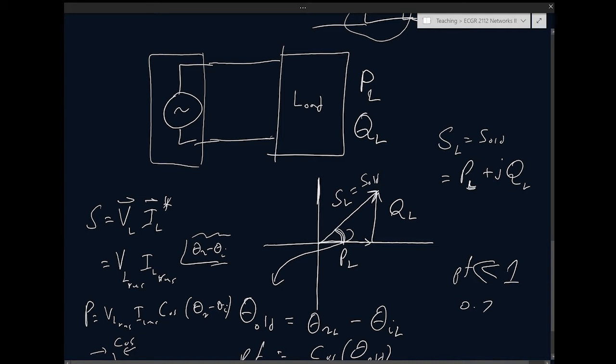Resistive loads are not reactive, they are purely real, right? But that's a very wasteful way. I'm improving my power factor, that's correct, but I'm wasting a lot of energy burning it in the resistors. So I could put in a bunch of resistors here, and this will increase the power going into the load. It will be the power going into my machinery plus those resistors, and that will improve my power factor, but it's a very wasteful thing to do.